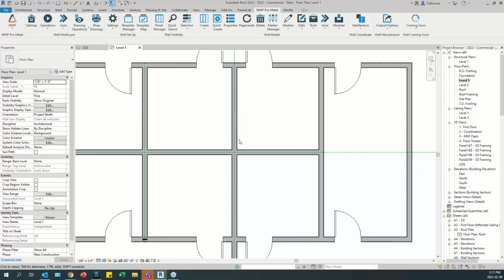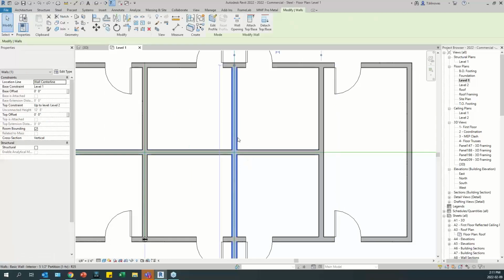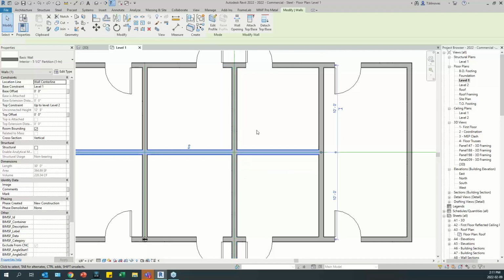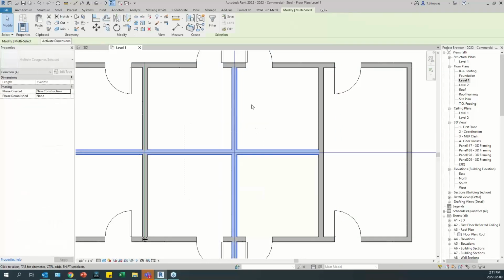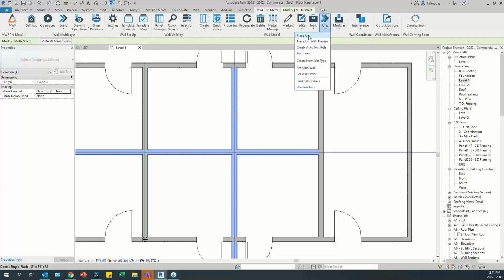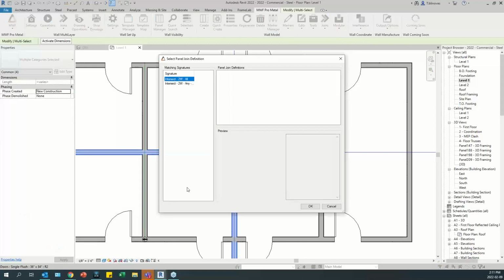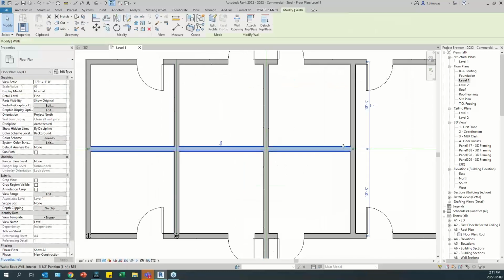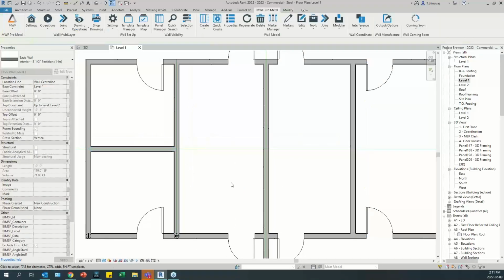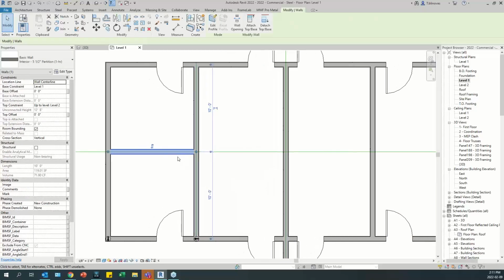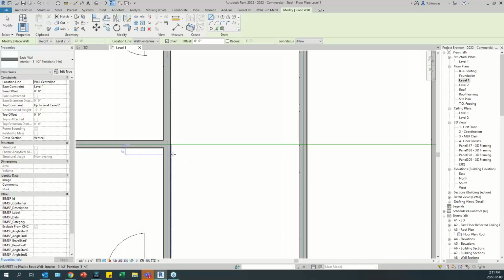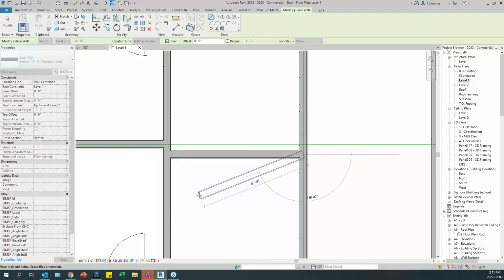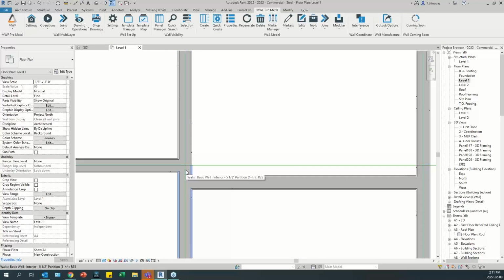And just like, for example, in this corner here, this is even a bigger issue because in this case, we have 2 walls only. That one is also not separate. So if I mass select this guy and I go here to place join, it's also going to identify this as 2 walls and it's not going to work out as well. Okay, so let's just drag this back like this. And one thing that you could do is let's just create similar. And you could just create this portion here a little bit off the center, and you can align this afterwards.